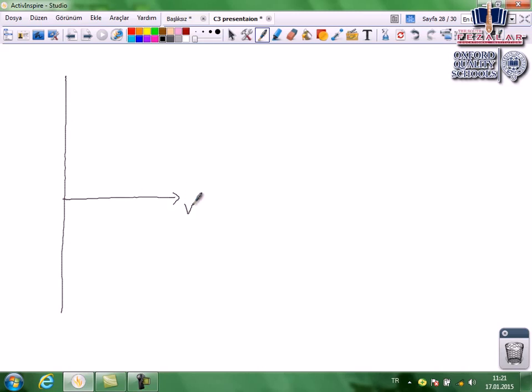We draw all voltages on the x-axis, let's say V, VL, VR, and all that. And there is IR, and in the plus y direction there is IC. In the minus y direction we have IL. As you see, again on the y-axis there are two vectors, so you will take the resultant of them.